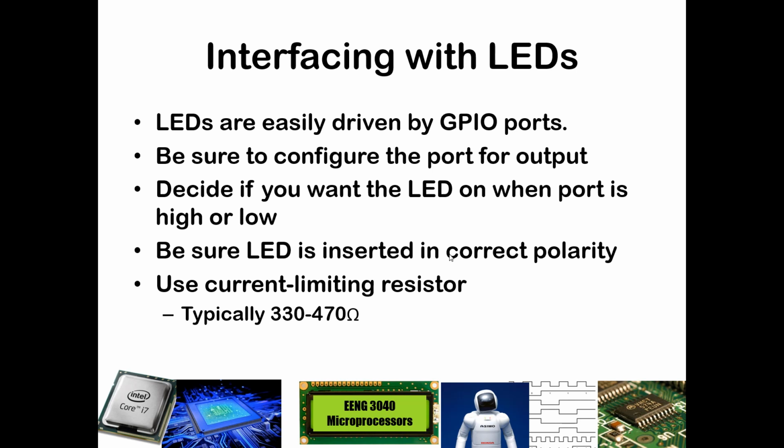So if you think about 5 volts being dissipated, with it being an ideal diode, we would have all 5 volts across the resistor. In a real world, a diode will dissipate about 0.7 volts. And so in that case, you're thinking about 4.3 volts divided by the resistance that you have there. So that will get you to about 10 milliamps if you use somewhere between 330 to 470 ohms, especially recognizing the tolerance in those resistors.